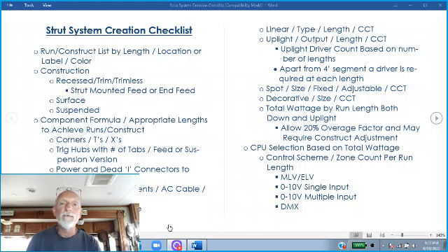Remember that we are magnetic low voltage, electronic low voltage, and a single 0 to 10 input, either of which can just be a switch, contact closure. We have multiple 0 to 10s totaling out at 4, so you can do up to 4 zones of that. And we have DMX. So remember that any of those are our choices, but you need to make that choice at the front end. It can be changed out in the field, but that's a little more challenging because you then have to rewire on the 0 to 10 side or add in the DMX side.